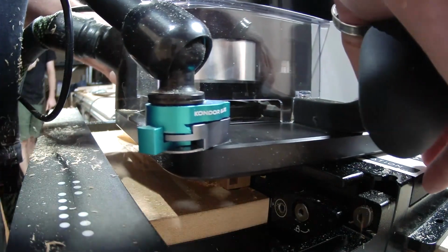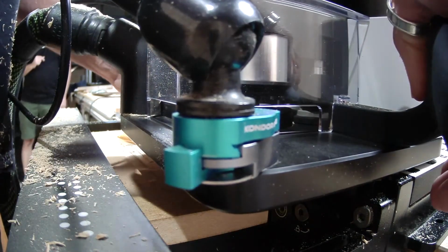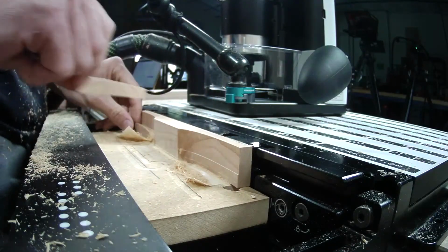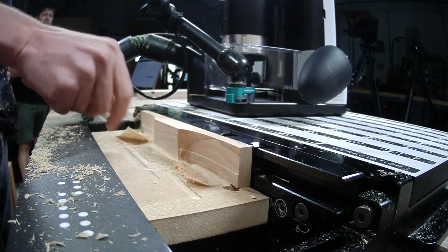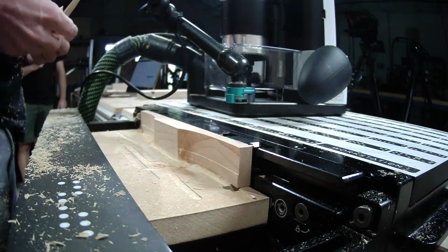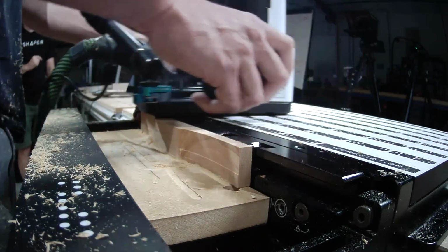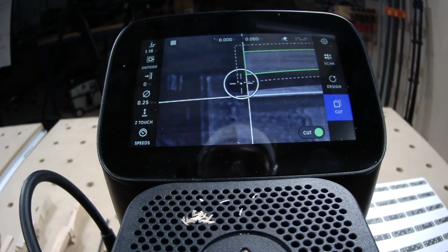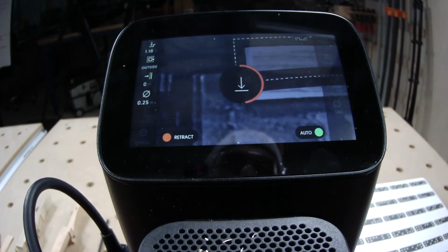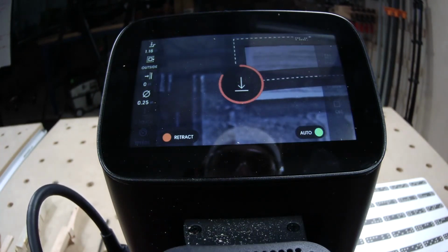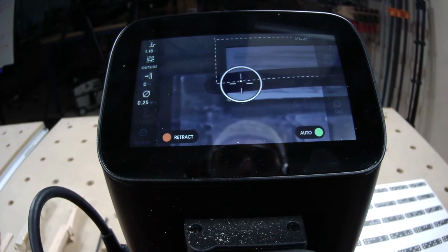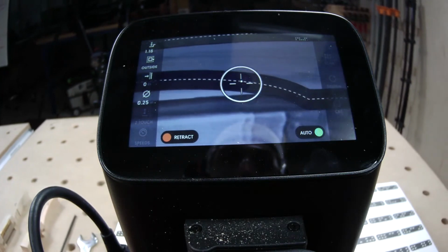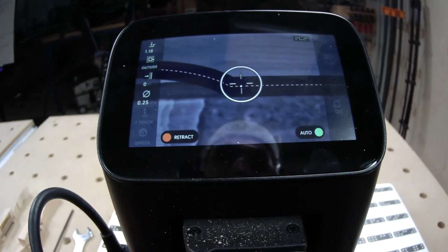So I think Sean is pretty much the whole way through here, and we might be able to see a tiny little seam between the two areas where he was cutting that he'll be able to sand out. But that's just a little cheat to get you a deeper cutting depth without bringing in a different cutter than the stock one. So I can't actually see the settings there. He might be coming back and doing one more kind of air quotes finishing pass there, just to get rid of that last little piece of material.